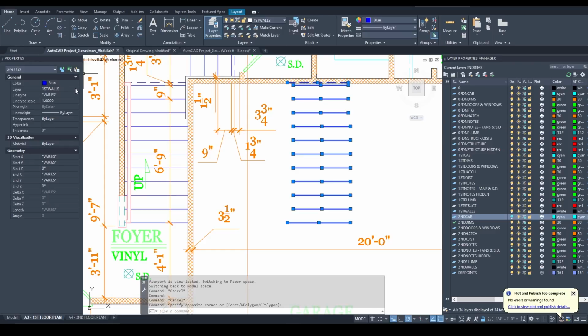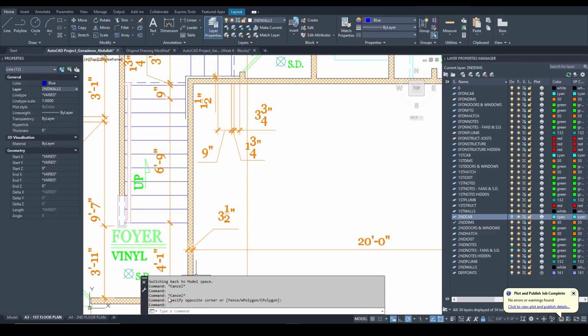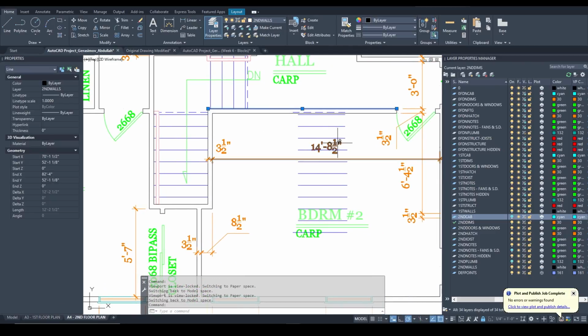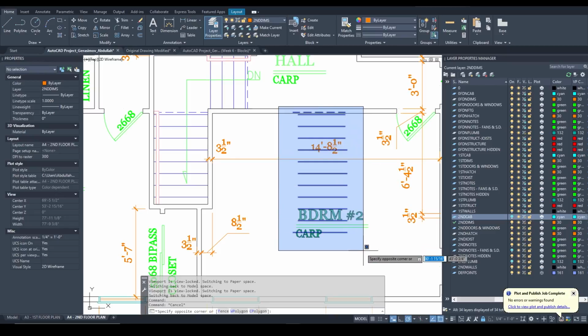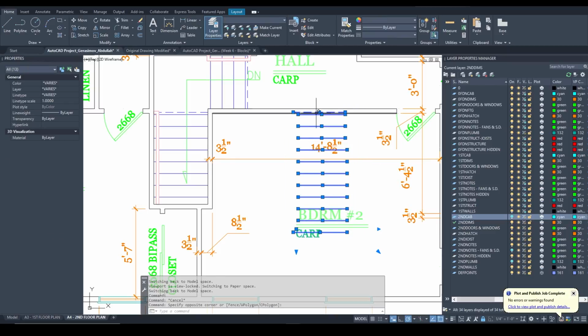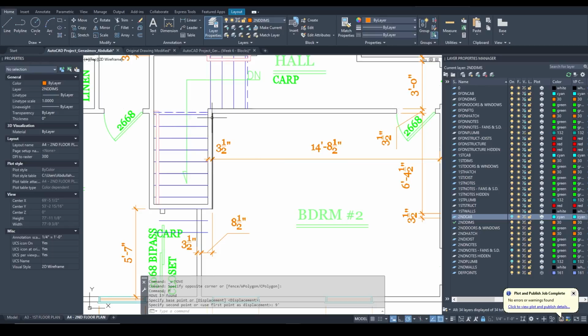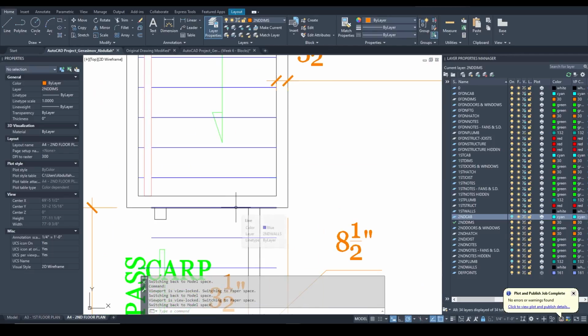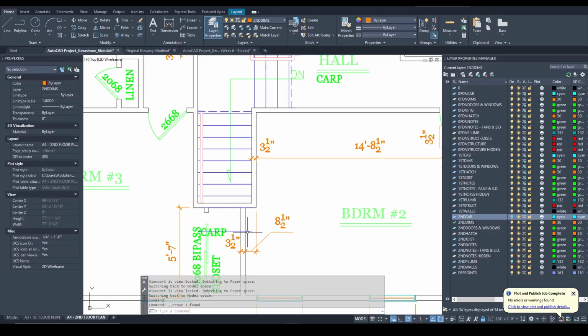viewport. So I copied these exact risers and move them 9 feet, and I'm changing the layer of all of them to second walls. That's the only thing that I'm changing. Now, if I go here, those risers are already in place, and I move them 9 feet, and they should stack up exactly where I have had them shown before. Those that are overlapping with your interior walls, you can remove those because those we cannot see. And this is the final look.